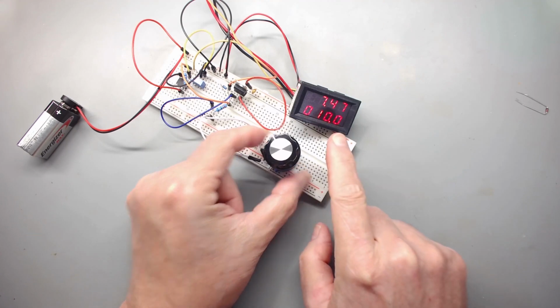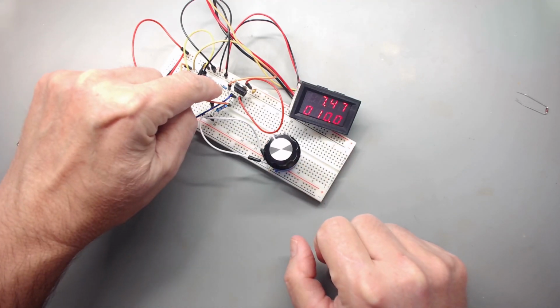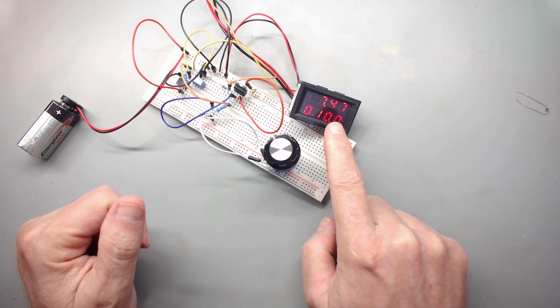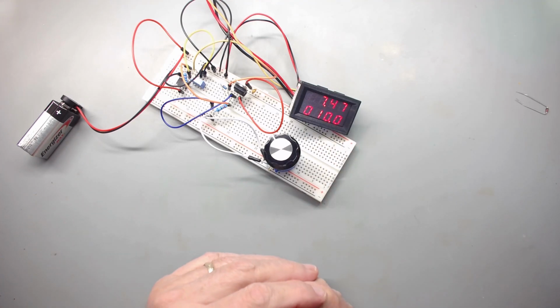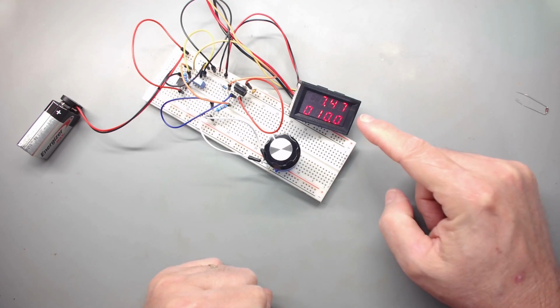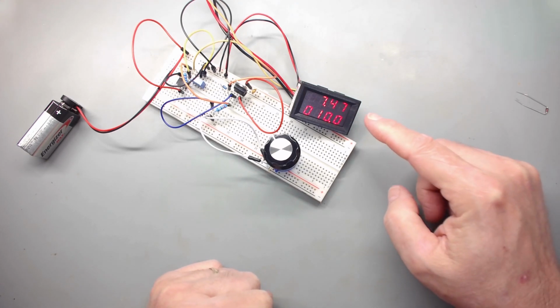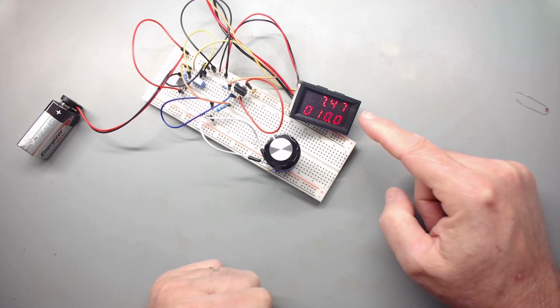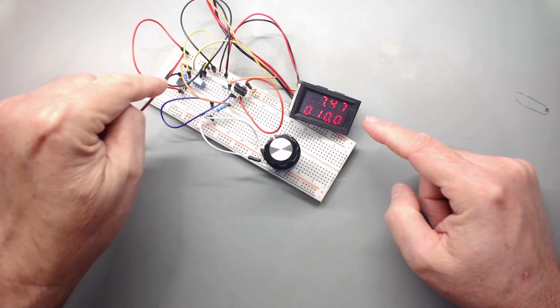this diode that's plugged into the board right here is reading 7.47, which we know is 10 times the voltage, right? So it's really 0.747, but that gives us all the way down to our 1 millivolt, which is what I was looking for. That's where the op amp comes in.